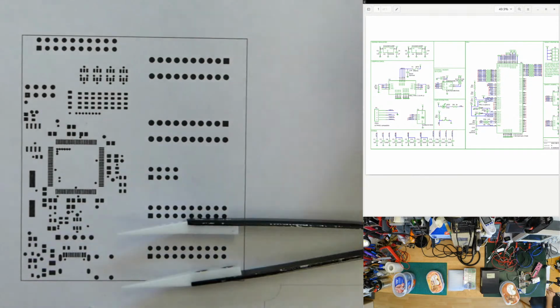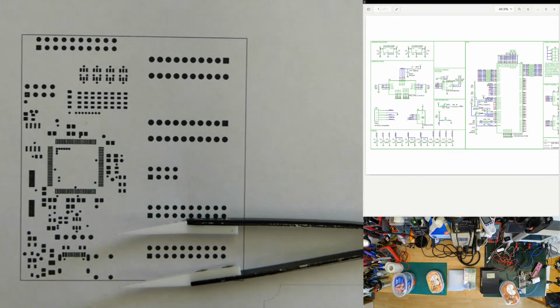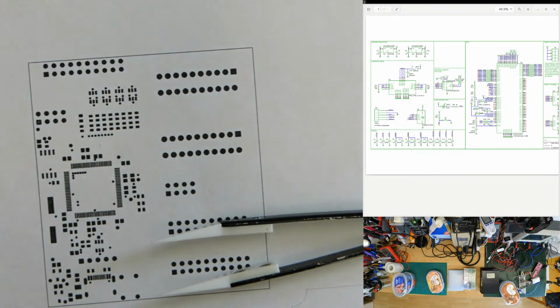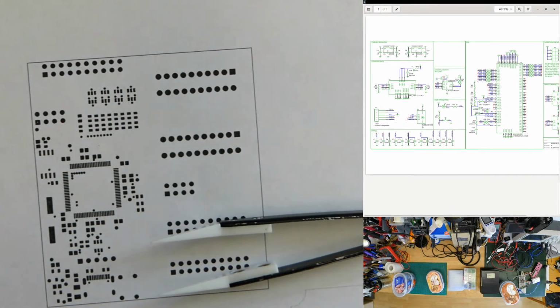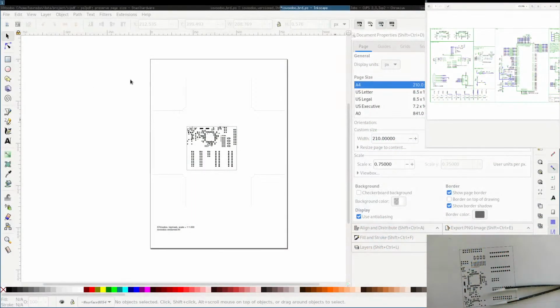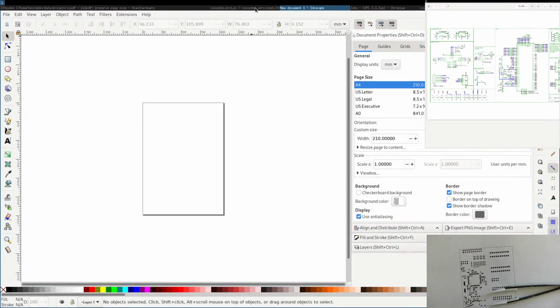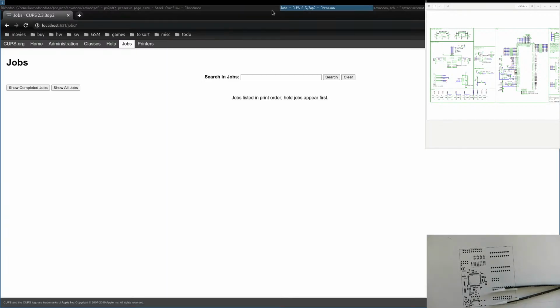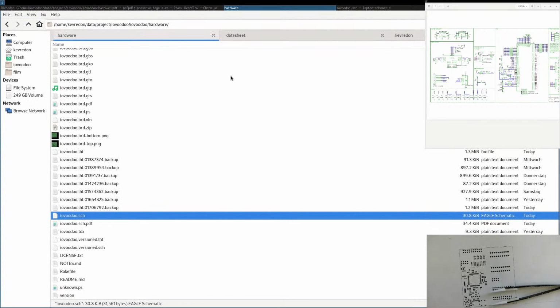This is done. Check. See, we started 1.5 hours ago checking if we can order things. We finished the routing, we finished the board layout, and we still are checking if everything is okay. But doing it now saves a lot of time afterwards. Let's go back. We don't need this. We've checked the footprints. They are fine. Well, the new footprints. All the other ones, I already know them. They should be fine. I'm sure there will still be a mistake somewhere. This never works the first time. But we can put all the chances on our side.